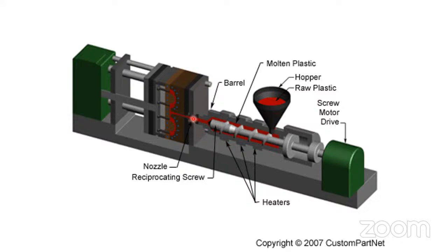Okay, you mean to say that during injection there is no rotation of the screw. Correct, only direct movement is there. And only during the backward movement is its rotation there. Yes, correct. The screw rotates anti-clockwise.